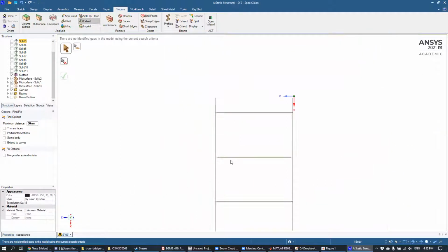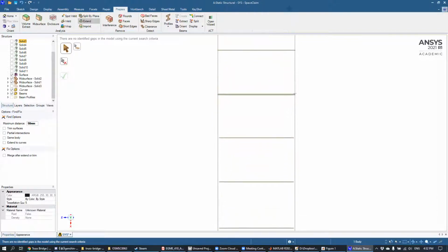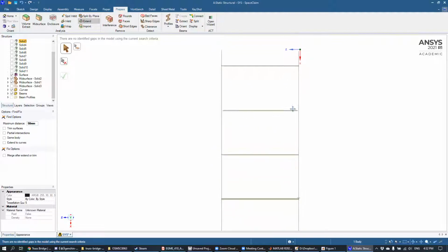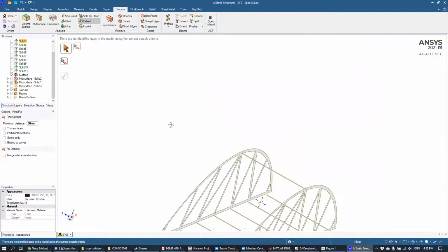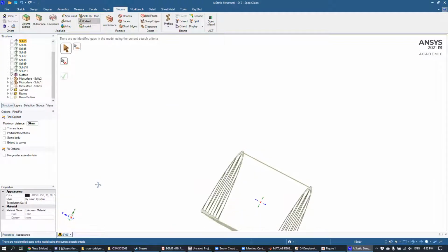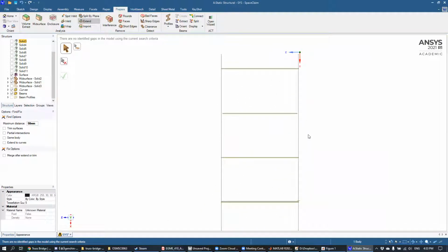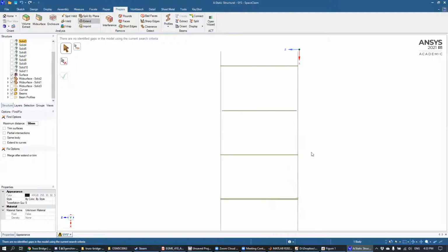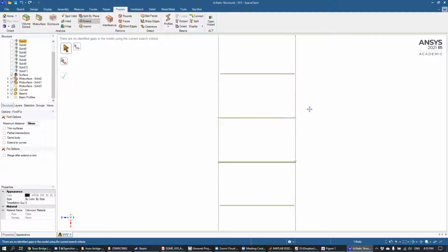All right, so what you can do from here is view the bridge by looking down the y-axis. If you're looking at the bridge just like this, you can go to the lower left of the screen, where the XYZ axis is. We want to look at things down the barrel of the y-axis, so we're going to click on the green Y right here. That's going to show us the top-down view, where we can clearly see which beams haven't been connected to the main one yet.